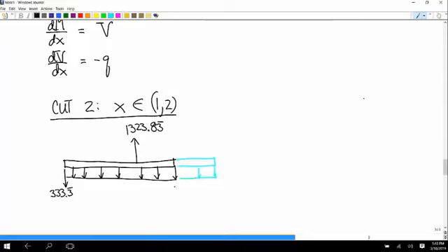That has a magnitude of 245.25 newtons per meter. And then that triangular distributed load goes from here to here. Does the end of that have a magnitude of 1,000 newtons per meter? We wish, yeah, because it actually continues to there, and this is where it has a magnitude of 1,000.